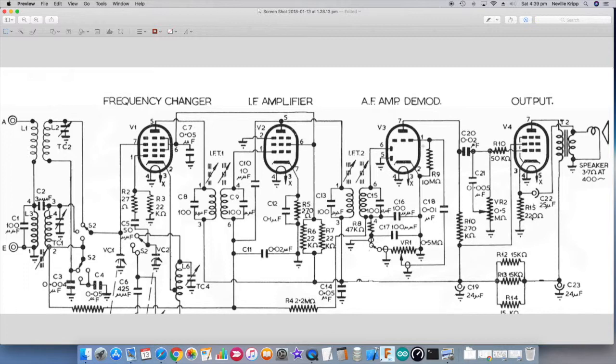So the triode is just used as a simple amplifier. At the anode of that particular valve, we'll have a slightly greater audio output signal. And just following across that signal, note there's a capacitor here which is feeding to the grid of the power pentode output stage. Also in amongst the circuitry on the actual grid of that output stage, we have a series of capacitors and resistors. It's just a simple tone control on the radio where it just reduces the amount of high frequencies that are fed from the output of that preamp stage to the power stage.